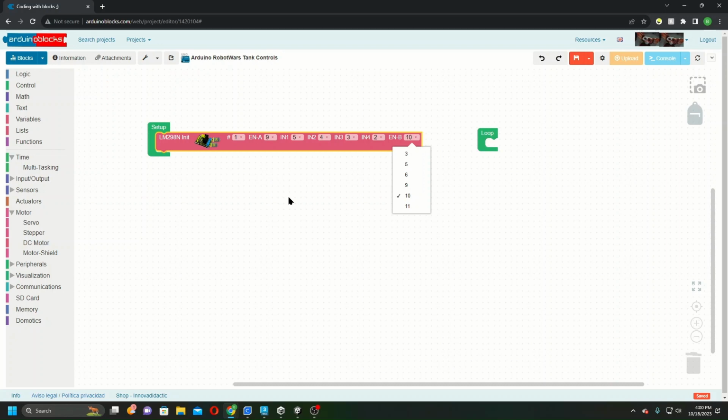A lot of explanation there. Sorry about that. Anyways, at the end of the day, pin 9 and pin 10 are the ones that are going to tell our motor how fast to go. Pins 5, 4, 3, and 2 are the ones that determine our direction.